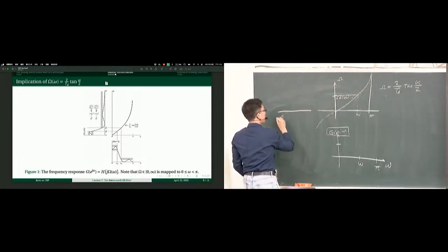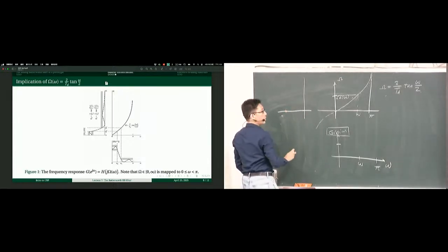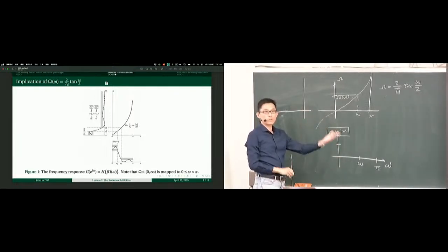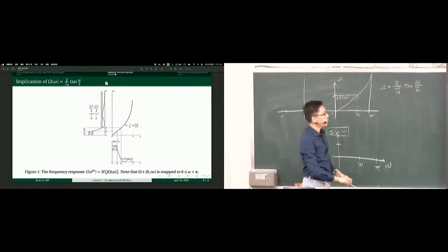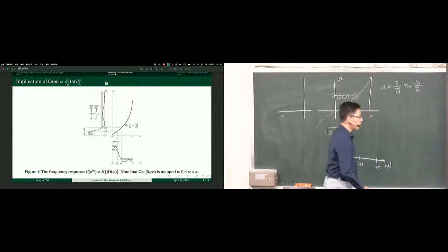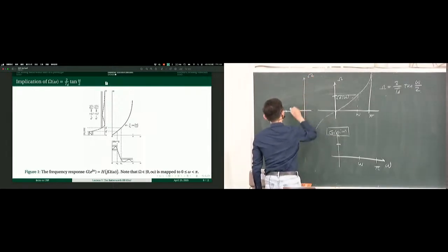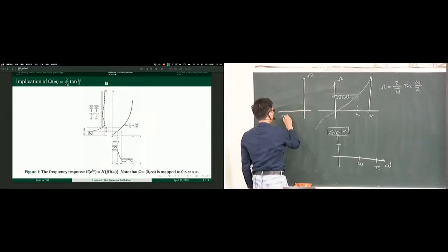So that's why here in the textbook we have this drawing. Now if we just rotate the frequency response plot by 90 degrees right here, just do a 90-degree rotation, turn it 90 degrees, then here we have the magnitude response, which is our prototype, |H(jΩ)| as a function of big omega. Okay, and what's our prototype?